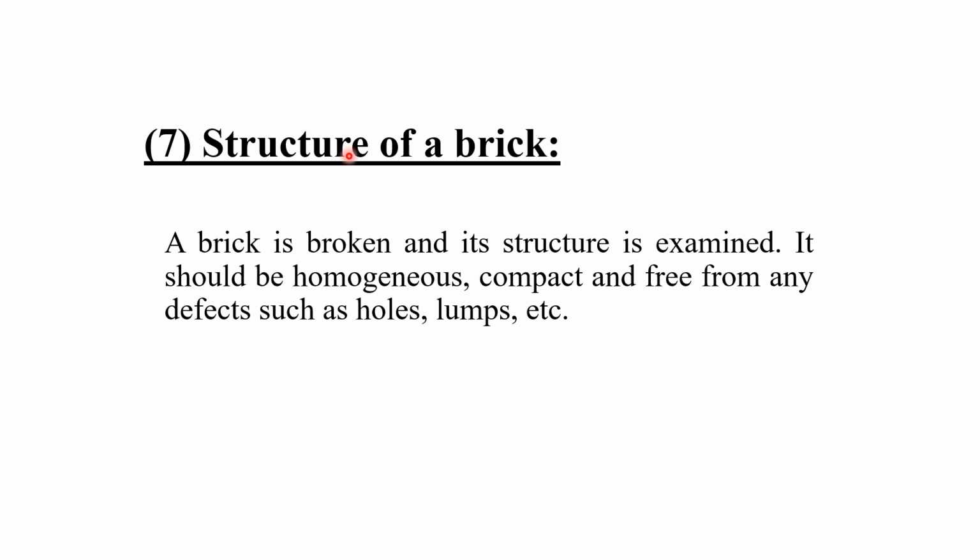Now the seventh test is the structure of brick. A brick is broken and its structure is examined. It should be homogeneous, compact and free from any defects such as holes and lumps. When we break the brick, if a homogeneous face of the brick surface is present, that is a good brick. If there are holes or lumps, for example due to some organic matter that decays after burning and leaves a hole in the brick, that is not a good quality brick. So there should be no holes or lumps in the bricks. That's the test of bricks.